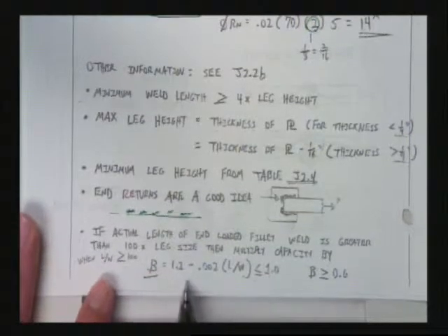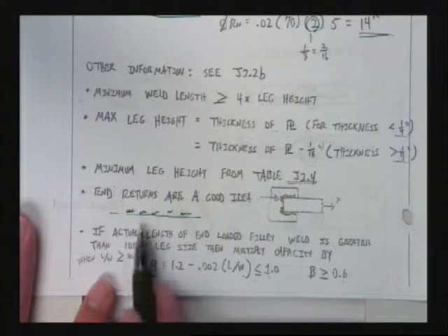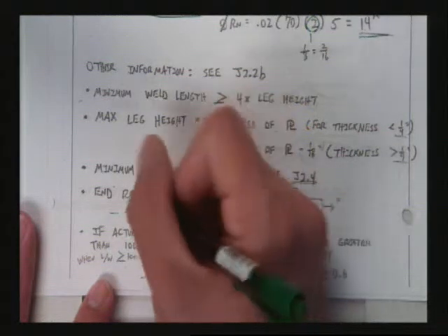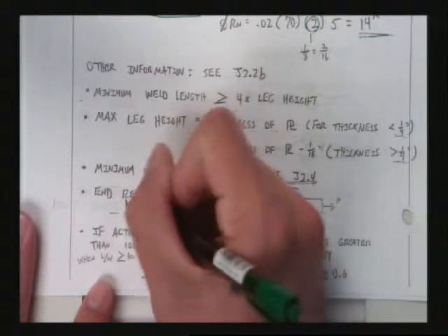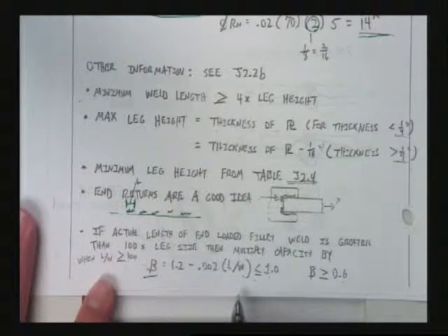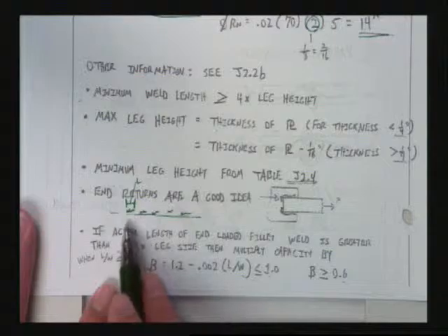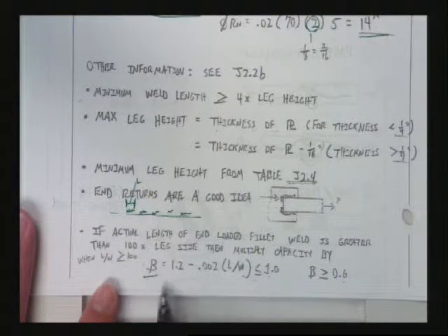Now, the way this equation is written and the way it's written in the AISC code, once one has a stitch weld, you would use this as your L, the length of your weld. You would use your W as, I think, the leg height of the weld that you actually compare it to, and your beta is never going to control with a stitch weld type situation, okay.